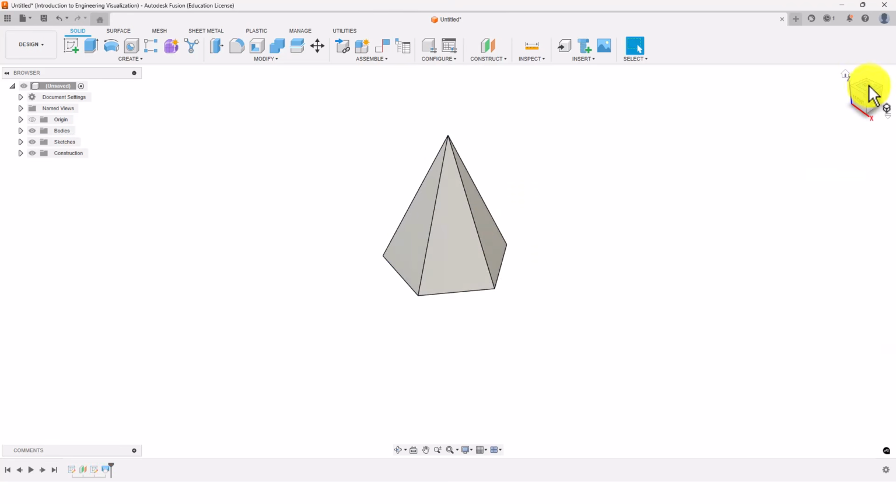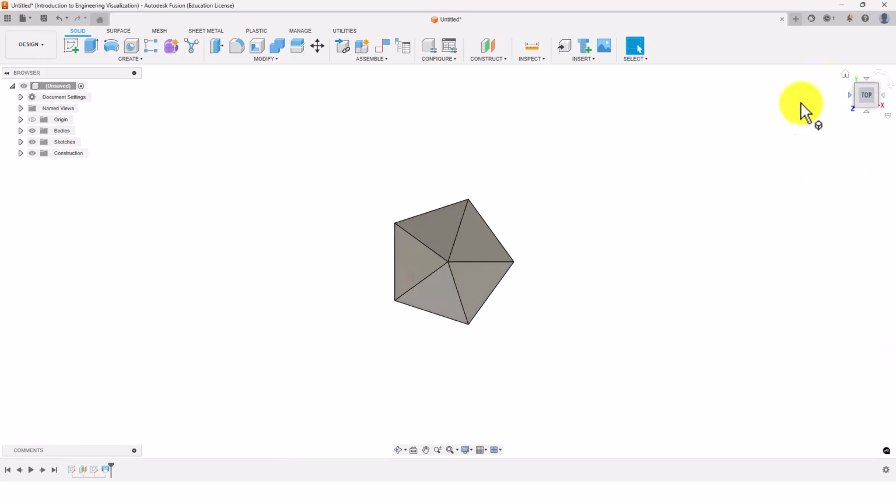and select the top view to make sure the corner is exactly on the right side. But here we need to rotate it based on the corner. So we need an axis. Here we forgot to draw the reference axis. So let us create that axis on the first sketch.